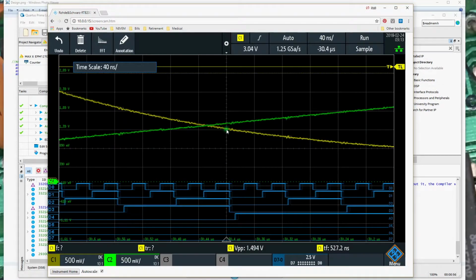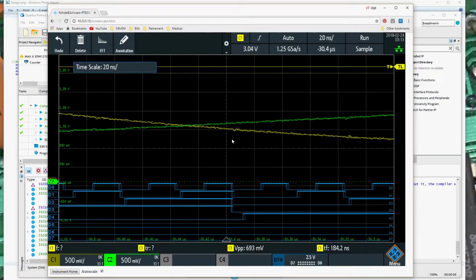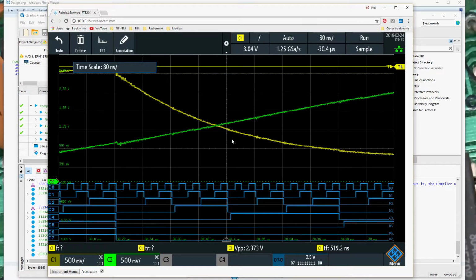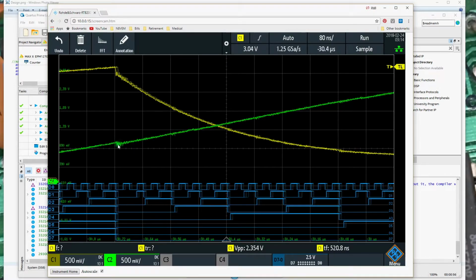We're not seeing the staircasing. Staircasing is bad. We do continue to have this rough transition right here. This is a point where we are shifting from all ones to all zeros. So we're outputting an FF into all zeros, and that rolls off.